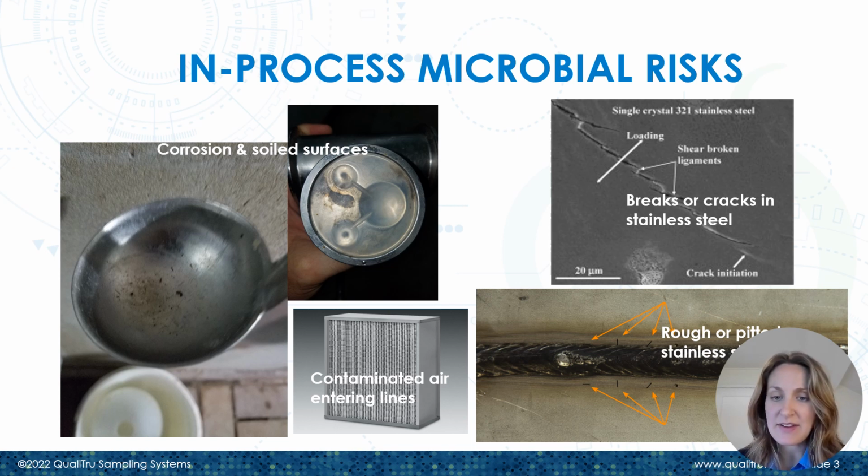It can sit, it can develop into a biofilm. In some cases, you might have poor welding work where you have rough or pitted stainless steel that over time will allow bacteria to cling to the surface. You might even have contaminated air if you don't have a good sampling plan or a good filtration plan in place. When you're blowing your line at the end of your cleaning process, that might introduce contamination before you start your new run.